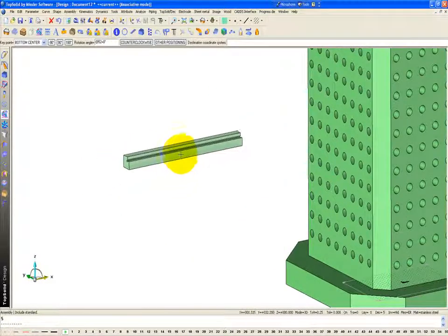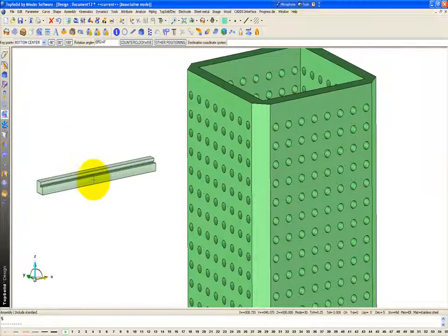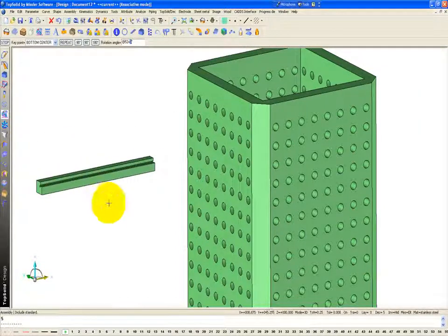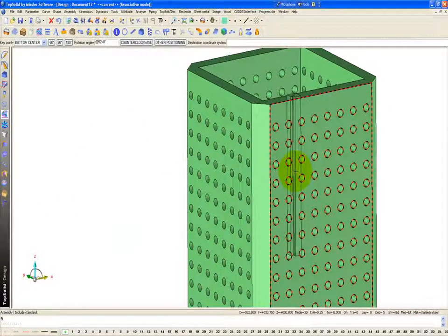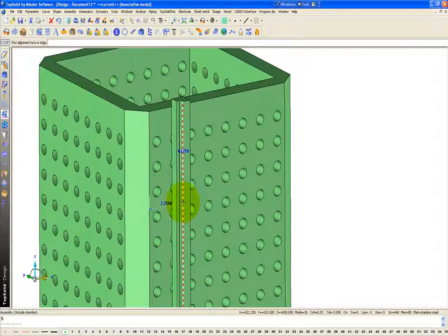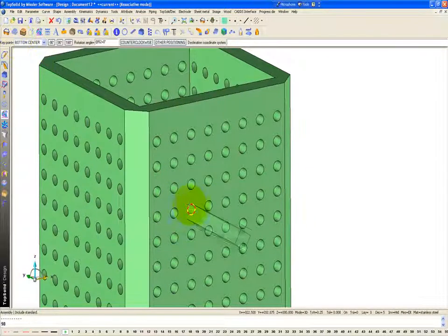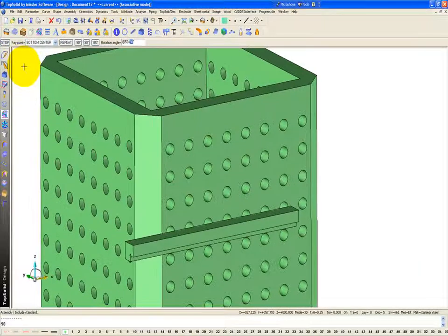and here's my fixture rail. Now what I want to do is lay my fixture rails out maybe vertically on my tombstone, maybe horizontally, don't know yet. So I'm just going to click to locate it. Pardon me, I'm not going to click. In this case, if I just pick a point on the screen, or on the face I want to machine, it dimensions to the center of the part. I can say 90 degrees if I want. If I go here, I can say stop and then say 90 degrees to rotate it.